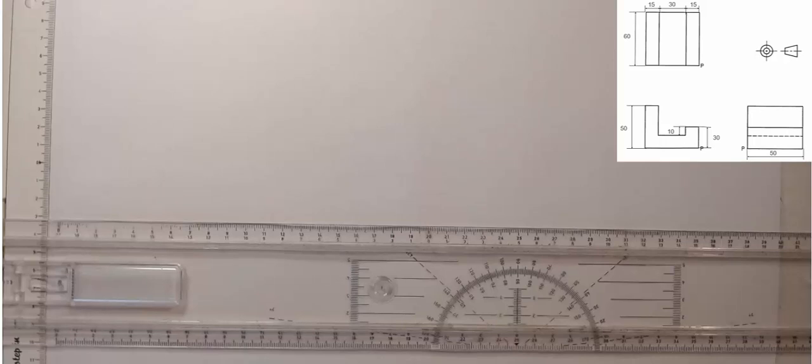Right. Let's look at how to draw this example 1 for 2-point perspective. Now, the first thing that we have to do is construct the top view, right? It says here the top view must have point P up against the picture plane so that the sides form a 45 degrees with the picture plane. Okay, so let's draw the front view.